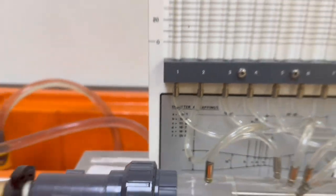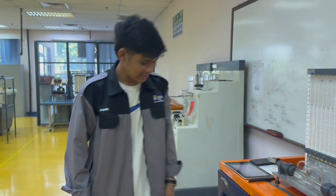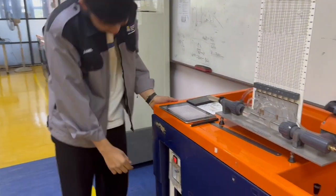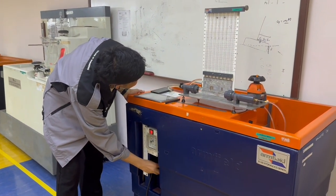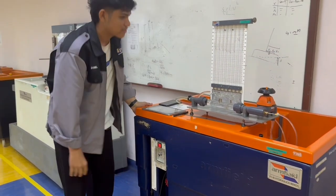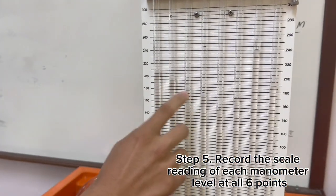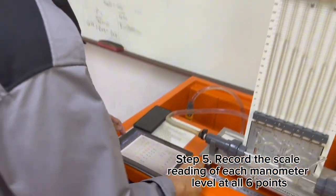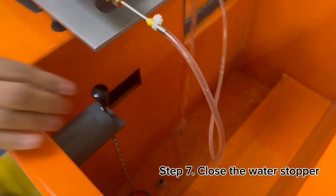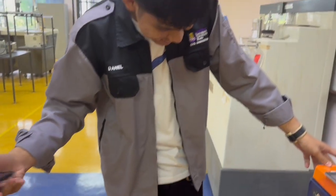The next part is how we collect the data from the apparatus. After that, you need to open the valve and carefully adjust the inflow valve and outflow valve to get the flow with high and low manometer levels, and record the scale reading of each manometer level at all 6 points. After that you need to close the water stopper.